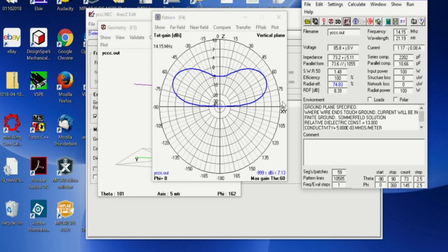And you can see that because this antenna is roughly a half wave off of ground at its frequency, the angle is about 60 degrees. So that's not great. You can also see that there's very little radiation right on the horizon. For DX, we'd really rather see the peak of this be down in the very small numbers of degrees, like around 8 degrees.